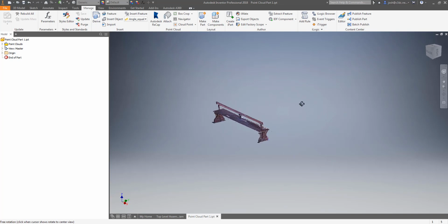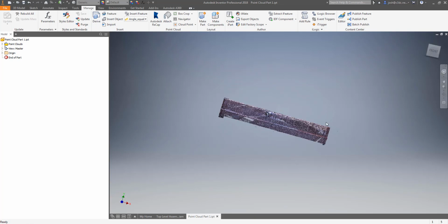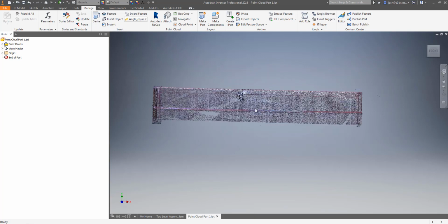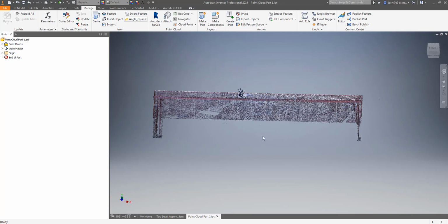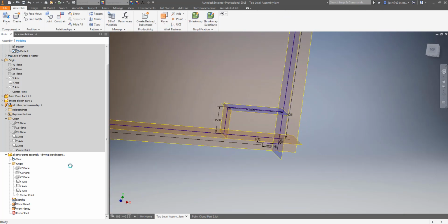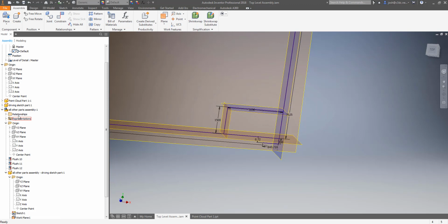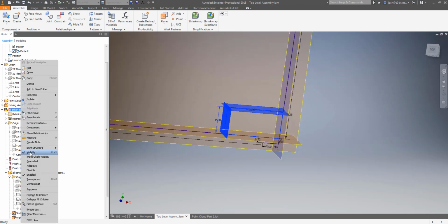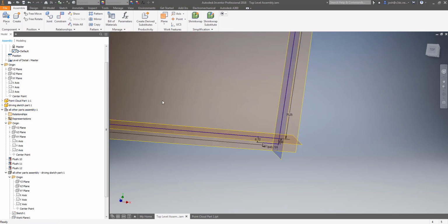Due to the way I want to work with this bench seat model downstream, I want to make a part to do the 3D solids in and have the origin of that part centered in the seat at the ground level. To do this, I will need to create some more geometry in the main driving sketch to constrain my bench seat part in. I do this using the same methods as we used to create the first sketch.